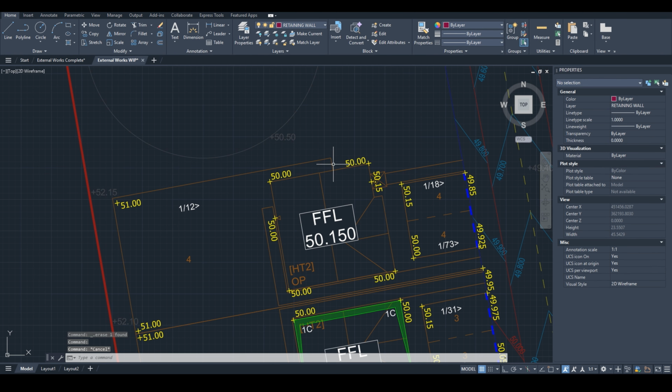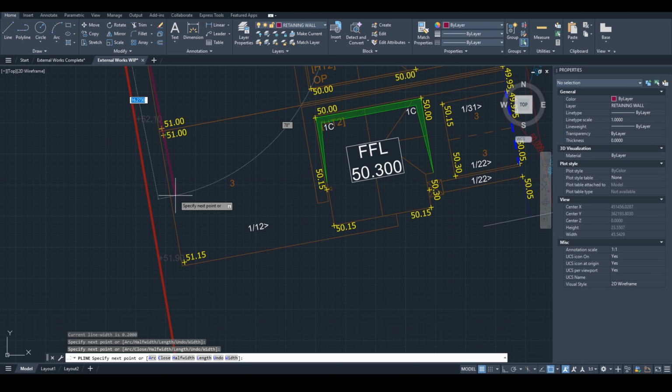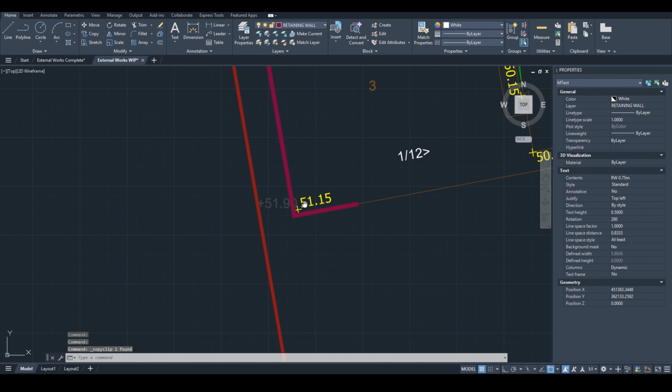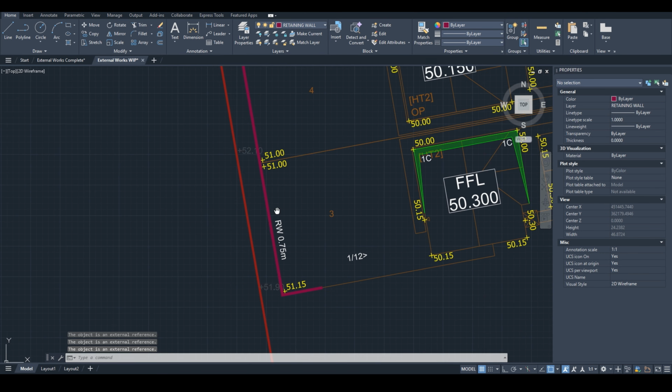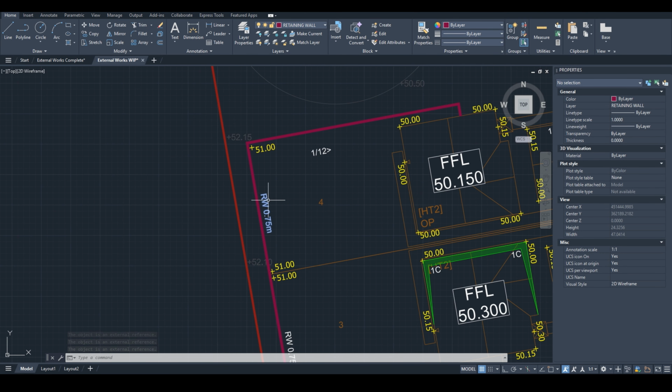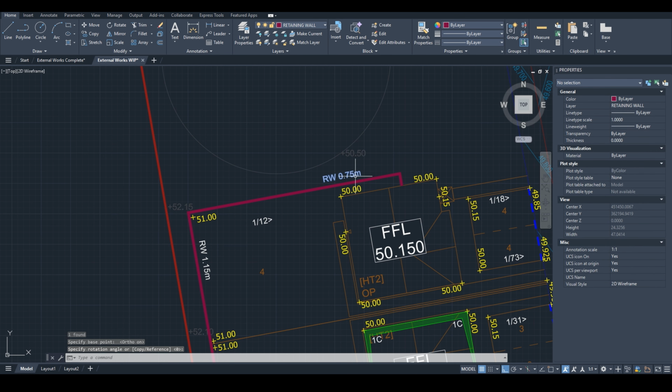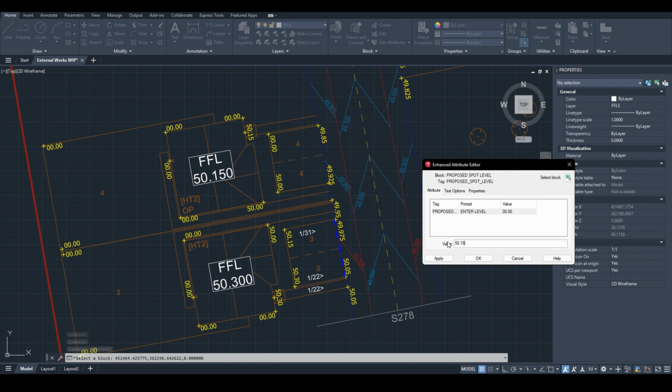To make up for this level difference, I will show the required retaining wall. I will draw the full extent of the required retaining wall and annotate the height of the wall at the back of each garden, and when there is a turn in the wall, the height of the wall is simply calculated by taking away the lower level from the higher level. And that is these 2 plots complete.